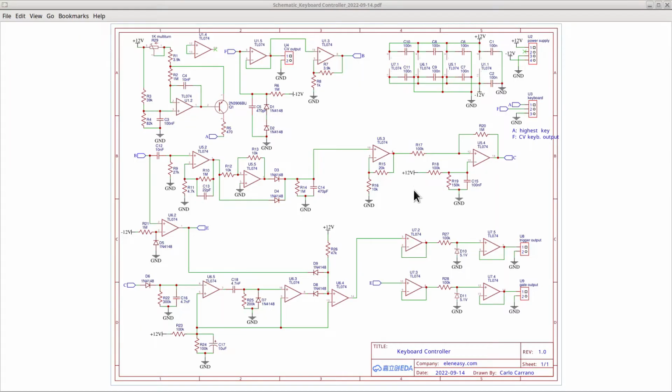To make this effective then, we first use another impedance adapter on the output of U5.5. At the same time, we also increase the signal to double its current amplitude, just to make sure that the actual signal is high enough to distinguish it from the noise. This is done through U5.3, which is configured as a voltage amplifier with a gain of 2. The output of this amplifier goes directly into U5.4, which is configured as our comparator.